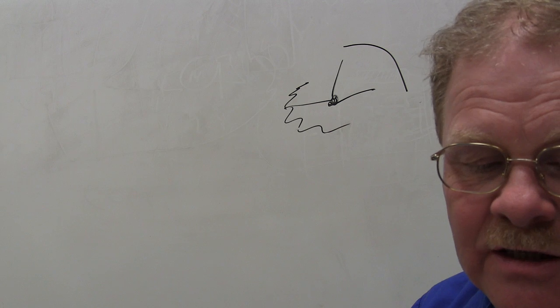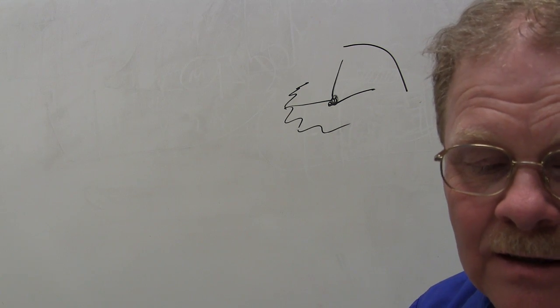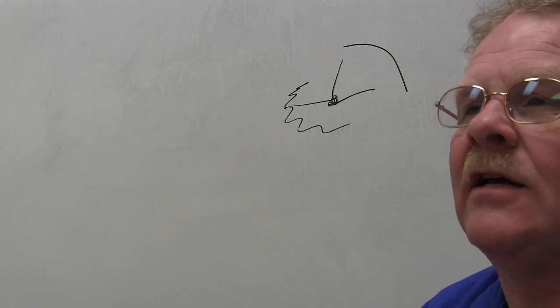Two technicians are discussing Karman vortex sensors. Technician A says they contain a burn-off circuit to keep them clean. Technician B says they contain a movable vane. Who's correct about that? Both those guys are not right, they're totally wrong.